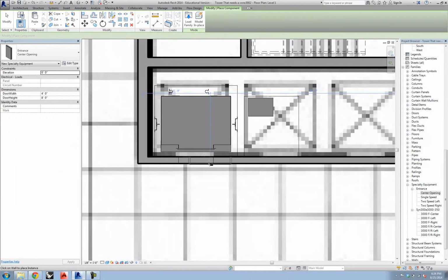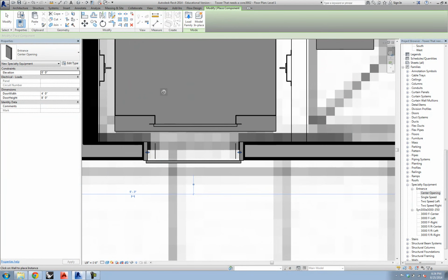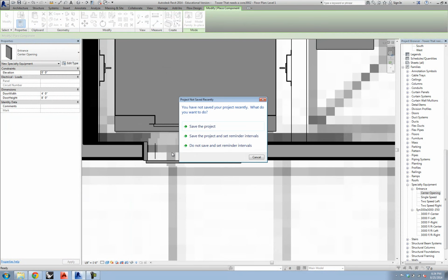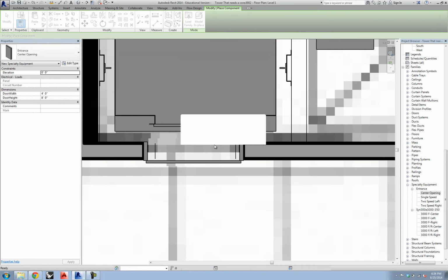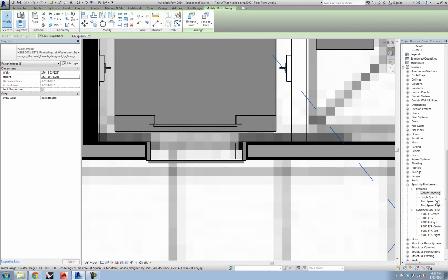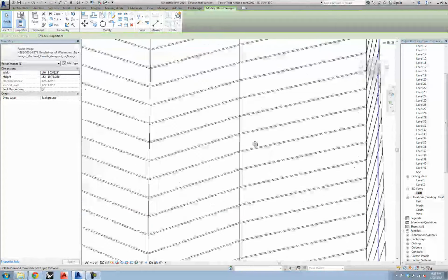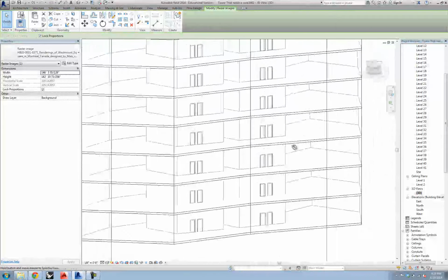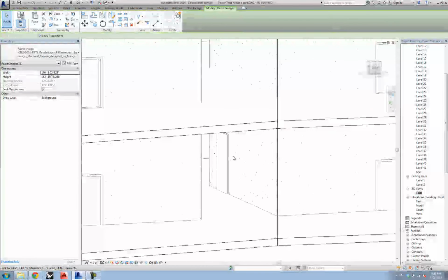And I'm just going to drag this in. And you can see it wants to basically, again, snap into the wall, and this time it cuts, and I get all the detail of the door and so forth right there, along with the, I'm going to nudge it so that it's aligned with the actual opening for the elevator. If we go into 3D, we can see what is happening down there. We've got an actual elevator door modeled in.